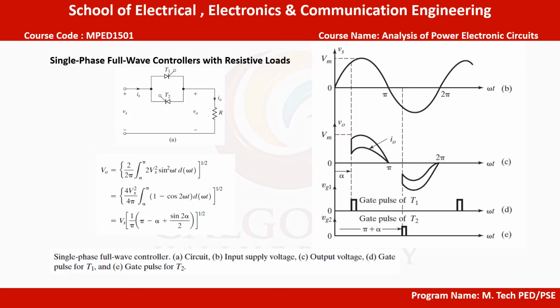The thyristor T1 and diode D1 conduct together during the positive half cycle, and thyristor T2 and diode D2 conduct during the negative half cycle. Since this circuit can have a common terminal for gating signals of T1 and T2, only one isolation circuit is required, but at the expense of two power diodes. Due to two power devices conducting at the same time, the conduction losses of devices would increase and the efficiency would be reduced.